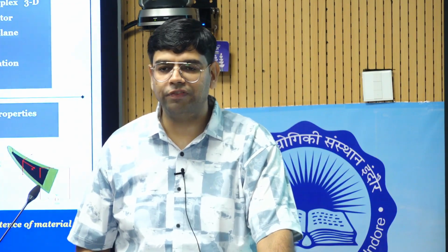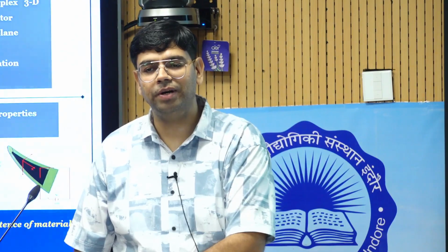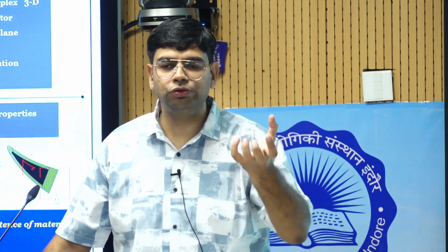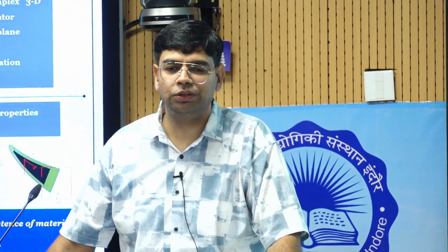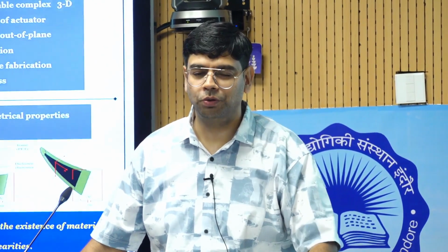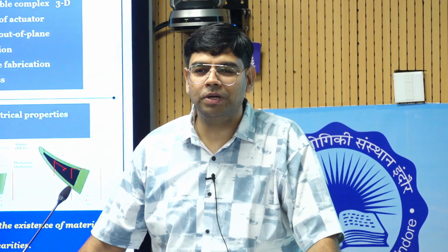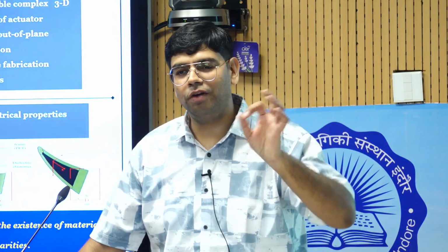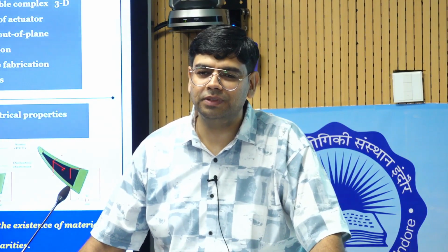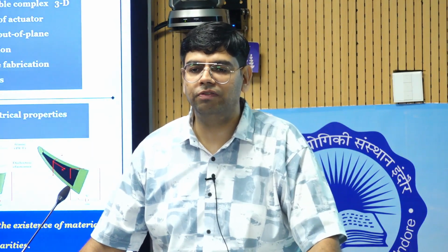Okay. So different applications you can see. This is a gripper made up of dielectric elastomer based minimum energy structure, and payload capacity I can tell you. Initially what we have done, we also provide some stiffening effect, so it can also hold some apple, some soft object, it can easily handle it. And I will show you one video where dielectric elastomer is also used to lift the dumbbell. If you are having a doubt about how much payload, basically the load it can carry, still a lot of advancement has been done. Even it can lift a dumbbell of around 5 kg.